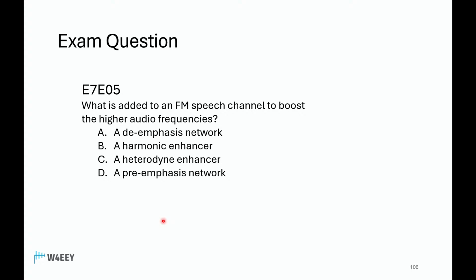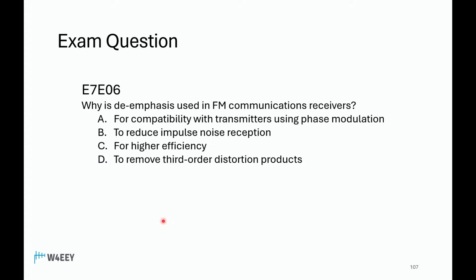What is added to an FM speech channel to boost the higher audio frequencies? Delta. Delta, we're pre-emphasizing the higher frequencies, and that would only be in the case of the direct FM case, because we get it for free, so to speak, with a phase modulator. Why is de-emphasis used in FM communications receivers?